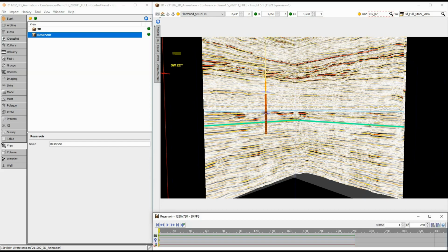A keyframe defines the full state of the view, including position and orientation, navigation, and other view display settings. The timeline editor will then automatically animate between keyframes based on how these change. The maximum number of frames can be set here. This sets the total animation length.